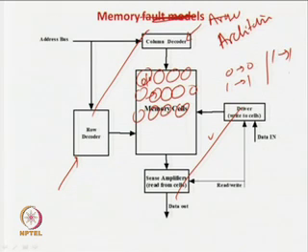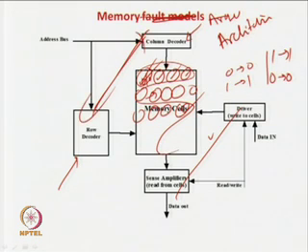If we do it for all individual cells one by one in a sequential manner, all the points will be tested, first this, then this, then this. The row and column decoder should be working properly, because otherwise you may get jumbled up data. If you want to access one point but are accessing another, you may get wrong data. So if you go through all these points in a sequential manner, the row and column decoders in another sense get tested or verified.